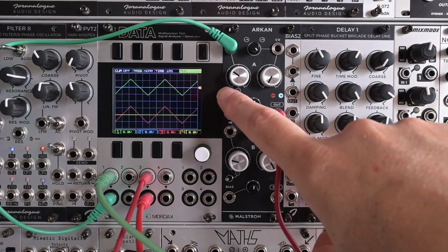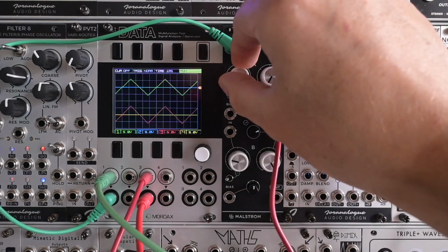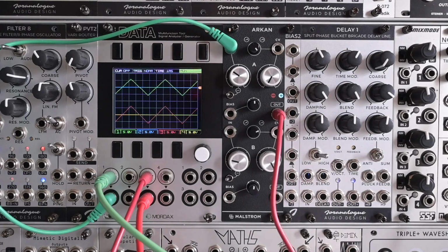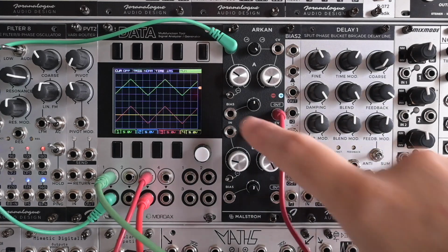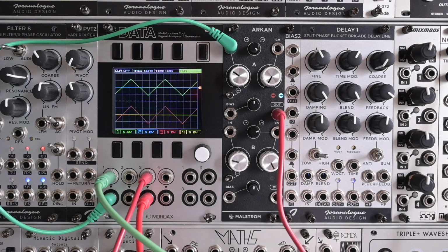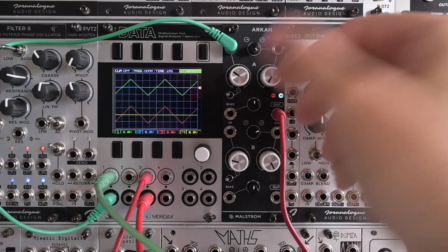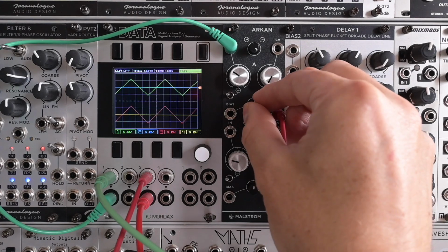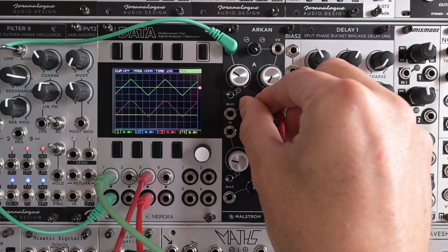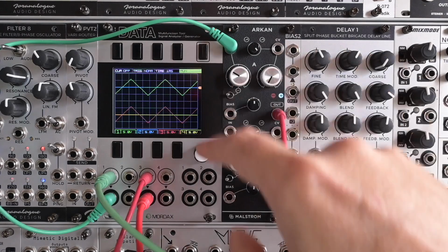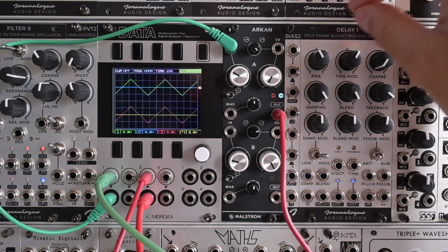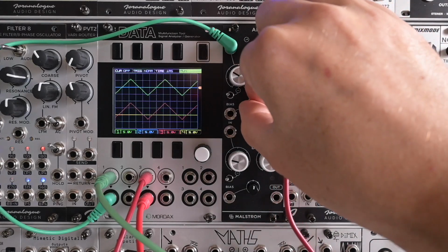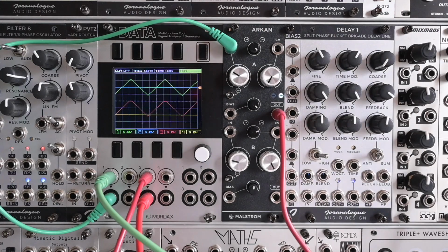There's no separate CV control over this switch here. Then there's this bias input and bias attenuator. When there's nothing patched in here, and you turn it to the right, well, or to the left, you add an offset. And if you take into account that 1 square on data stands for 5 volts, then you can see that I'm adding about 5 volts of offset to the signal.